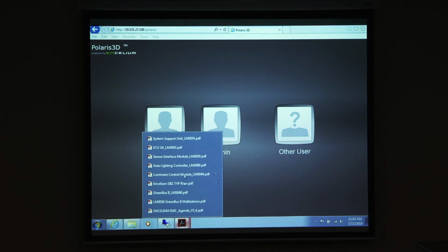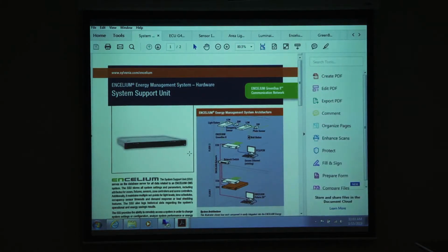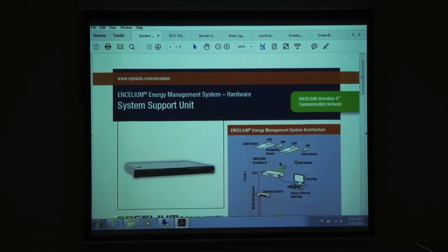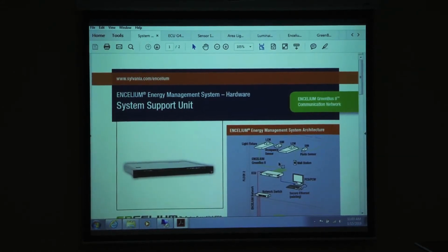If you have things like BACnet integration, building automation, in which they use occupancy status to control the VAV systems and whatnot, it's pulled from this system via Ethernet. As long as you're on the network, you can pull the information from here and trigger the VAV system using the occupancy sensors. Some people use the status of the zones to turn that on also. If you have an AV system, you can also integrate to the AV system from this box. So this box is a very important part.